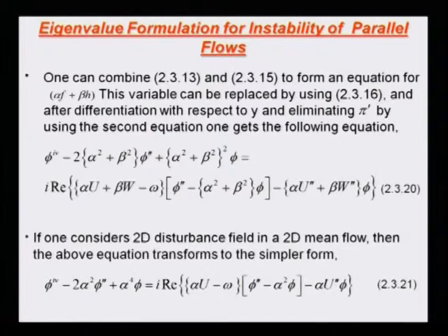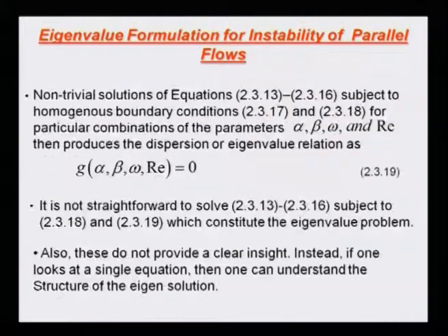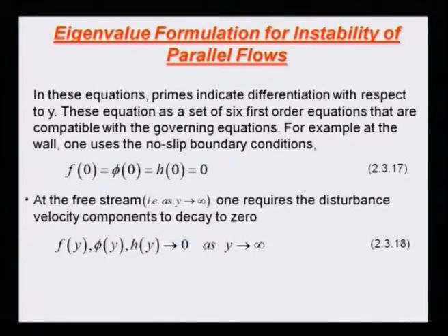This is a very famous equation now. Lots of work gets done starting from the Orr-Sommerfeld equation. Before we do that, let us say what we have. The equation that we had just now seen, the Orr-Sommerfeld equation, is a homogeneous equation, right? There is no right hand side term.